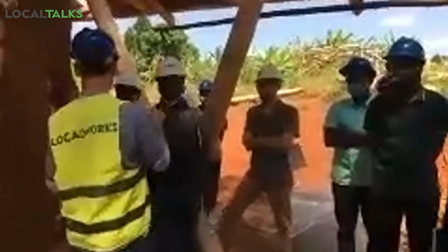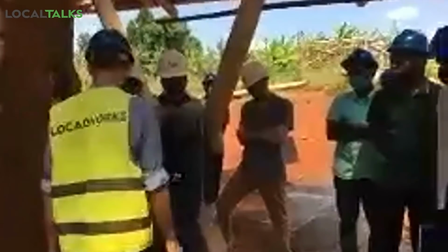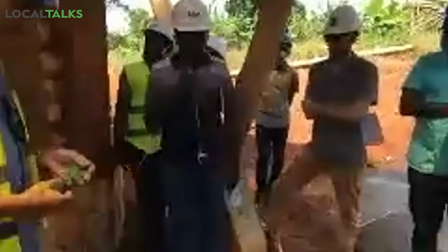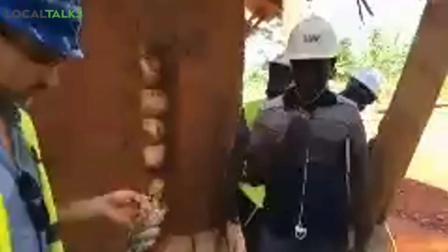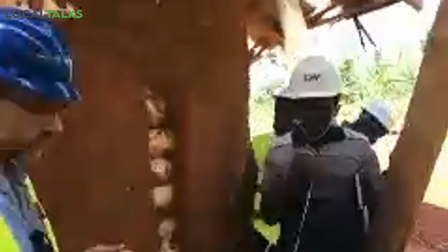I think Edson can say a bit more about the stability or the durability. I must say that if we get it correct, especially the final layer, the lime plaster, it's a rock if you get it properly. If you actually install it properly and cure it properly, it gives you a perfect rock. Of course, if you don't do it properly, then it will powder away, in my view. But comparable in strength, you can get as strong a plaster as you would get from cement.